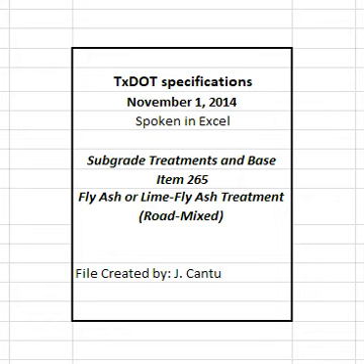4.7.1 FA or LFA-treated sections with FS. Cure the finished section for 7 days before adding another course or opening to traffic unless otherwise directed. Apply subsequent courses within 14 calendar days of completion of final compaction of the underlying treated course unless otherwise approved.